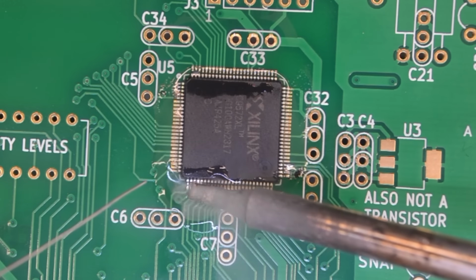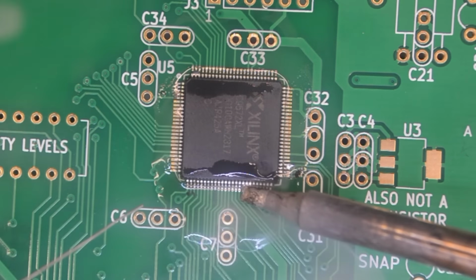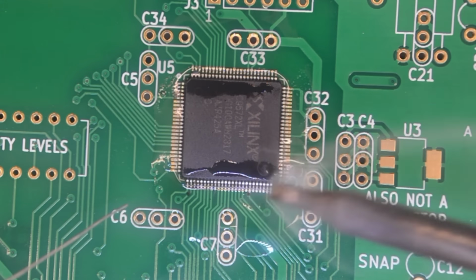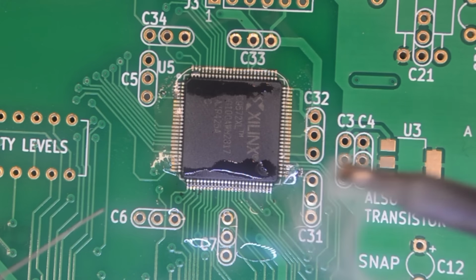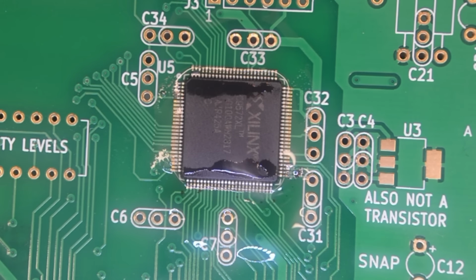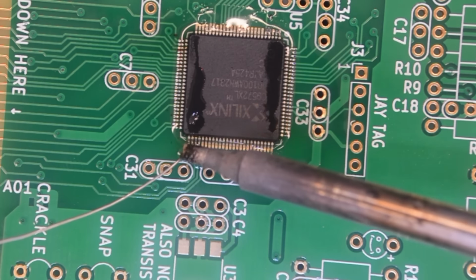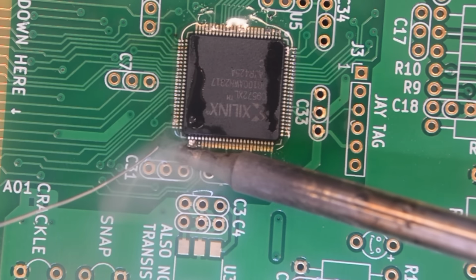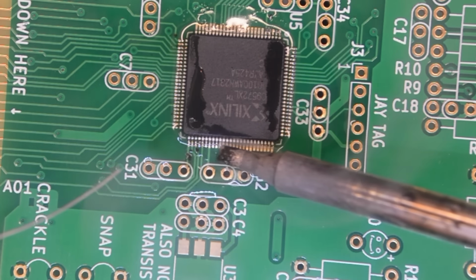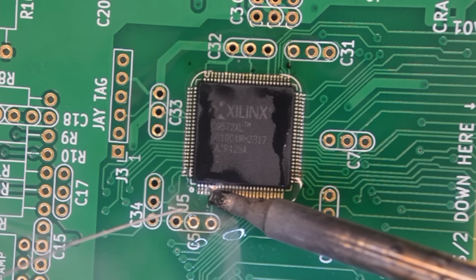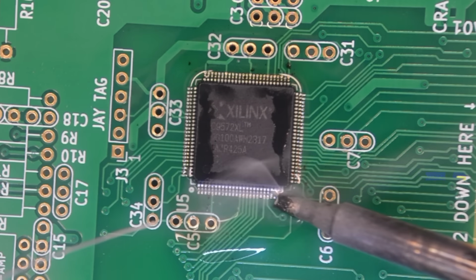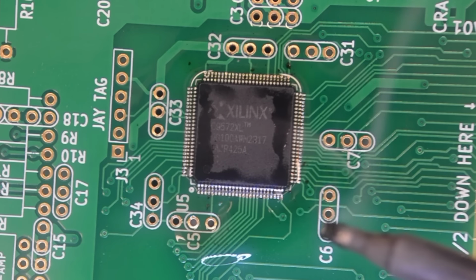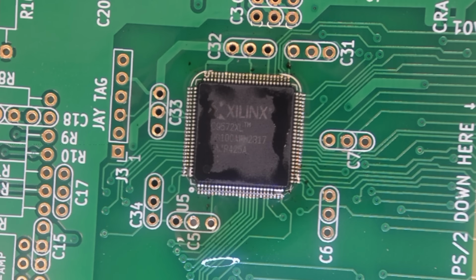There are other methods to soldering chips like this. But this is quick and easy. Now we can drag solder the two sides that already have a couple of legs soldered. The key to making this quick and easy is really good flux. And not applying too much force, because that will bend the pins.